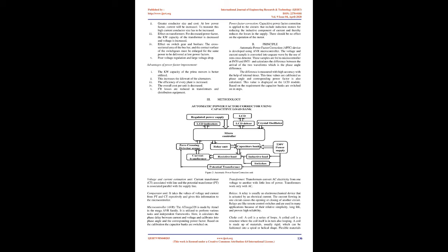If the power factor is less than 1, it means that extra power is required to achieve the actual task at hand. A poor power factor can be the result of either a significant phase difference between the voltage and current at the terminals of the load, or it can be because of a high harmonic content or distorted current waveform. Causes of low power factor.